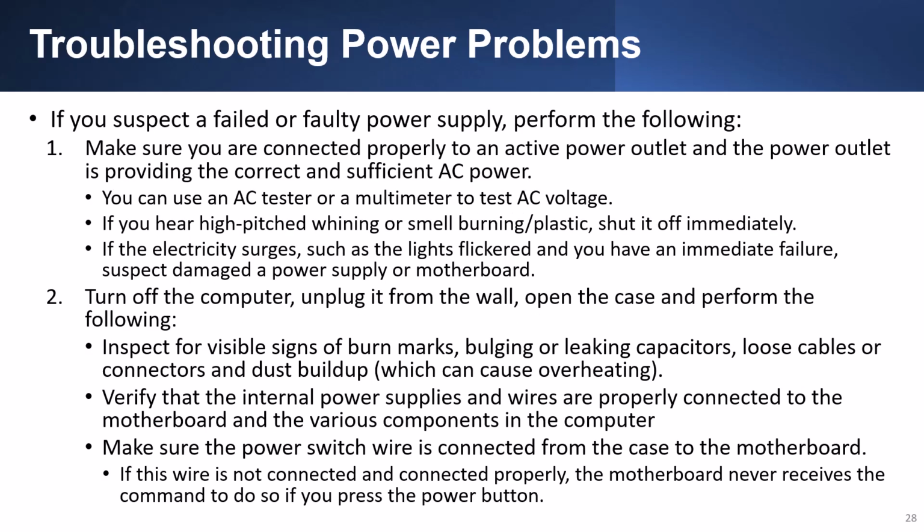If you suspect a failed or faulty power supply, perform the following. Make sure you're connected properly to an active power outlet and that the power outlet is providing the correct and sufficient AC power. You can use an AC tester or a multimeter to test AC voltage. If you hear a high-pitched whining or smell burning plastic, shut it off immediately. If your electricity surges, such as lights flickering, and you have an immediate failure, suspect a damaged power supply or motherboard.